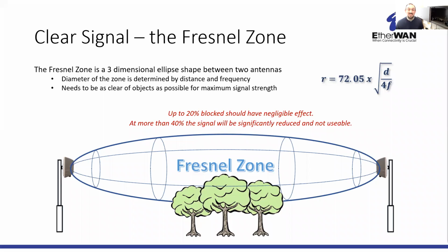So another one, if this hasn't been mentioned to you by the folks you're buying wireless radios from before, maybe something worth wondering why, as obviously this is a very critical element when you're setting these up and to be aware of when you're laying out that system design, knowing, hey, what is going to be the clearest signal path throughout these? Sometimes you might need multiple radios to route your signal around a large obstruction rather than just trying to blast the radio signal through it, which is really not going to be successful.